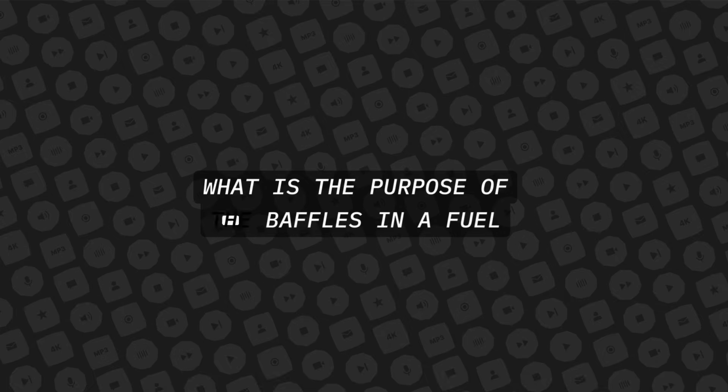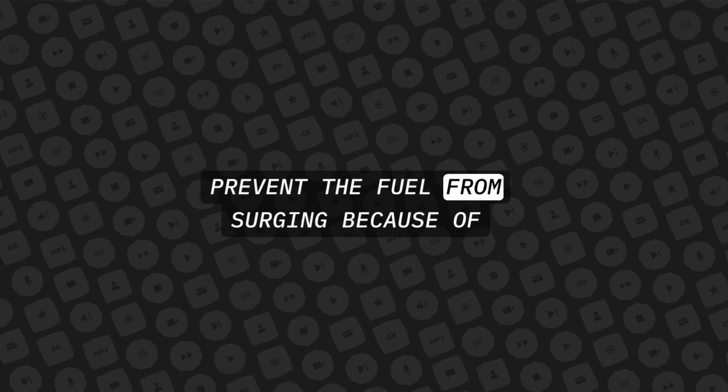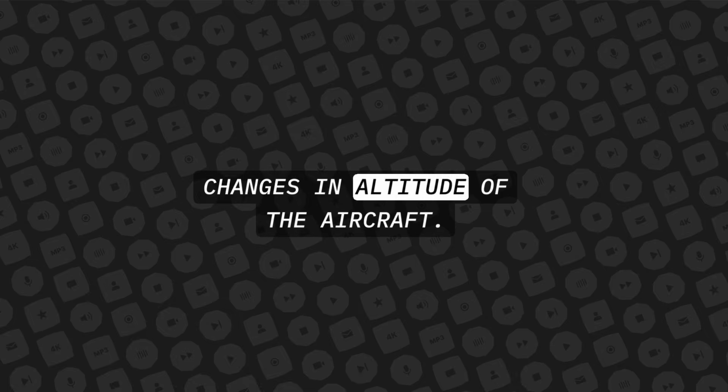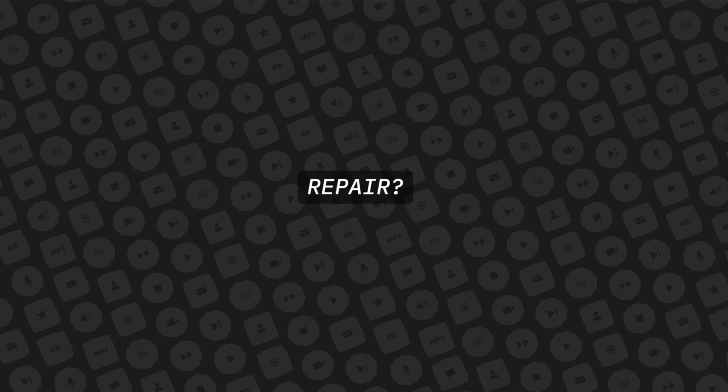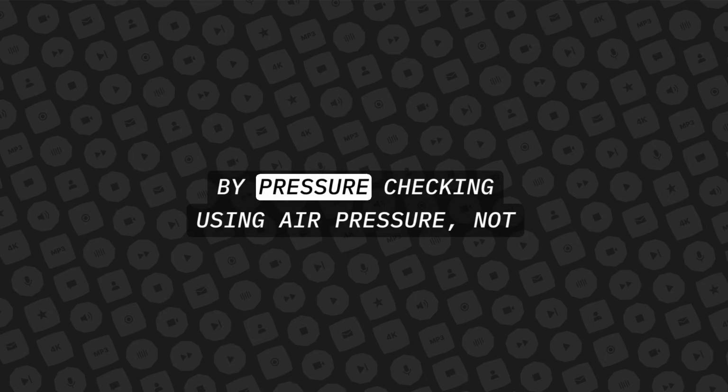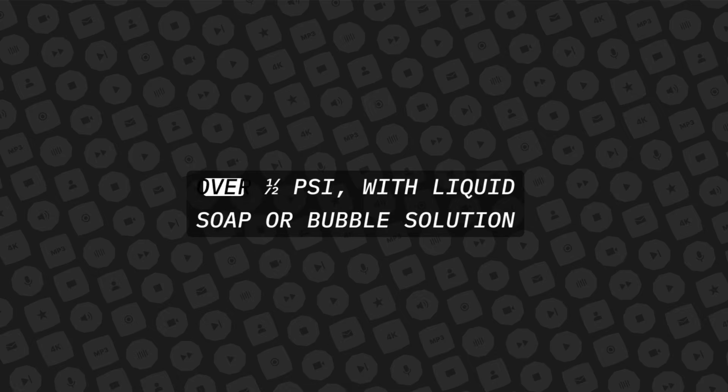What is the purpose of the baffles in a fuel tank? To prevent the fuel from surging because of changes in altitude of the aircraft. How can a fuel tank be checked for leaks after a repair? By pressure checking using air pressure, not over 1/2 psi, with liquid soap or bubble solution to identify the leak.